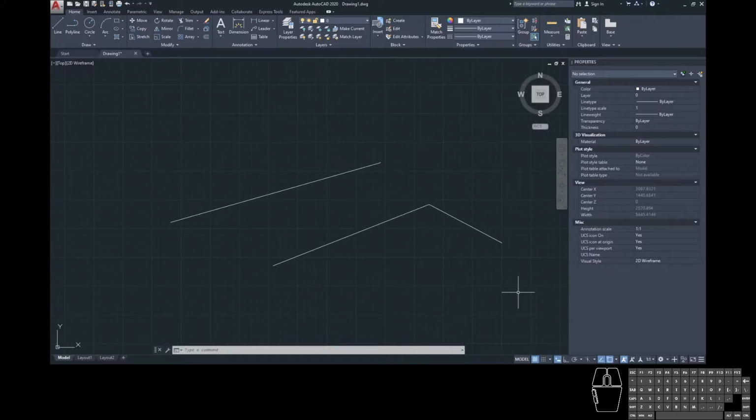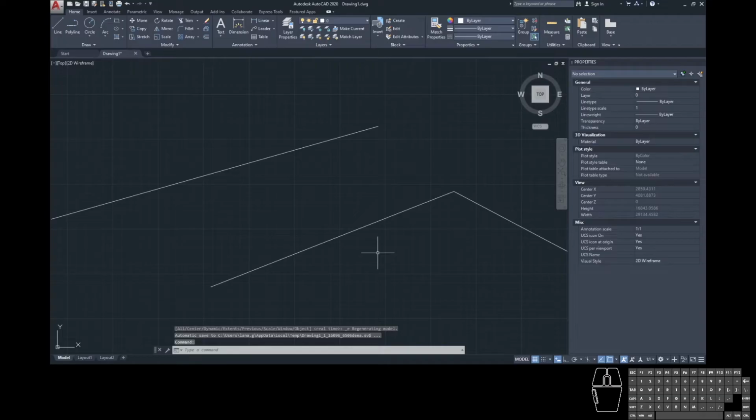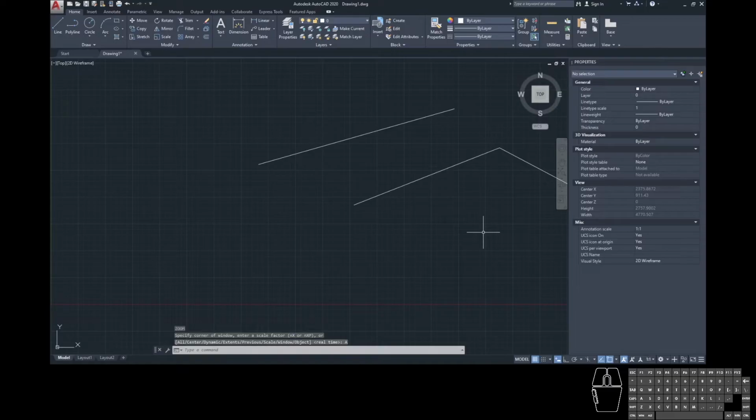The other zooming shortcut that you want to know about is this: when you are zooming out or zooming in, if you double click your mouse scroll wheel, you will zoom extents, which will just zoom to everything that you have in your drawing fully covered. The other way to zoom extents is by using the zoom tool. So the shortcut Z and then enter will bring up all of these different options for zooming. So you've got all, you've got center, you've got extents. This will give you that more specific control over a shortcut for zooming if you get lost within your file.